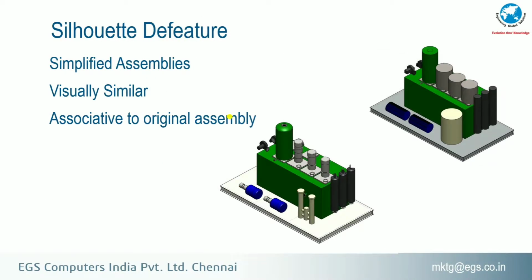Obviously, if you are working with a large assembly, opening that assembly takes much time. The reason is that it contains a lot of features, and every feature gets loaded while you are opening that entire assembly, right? To eliminate that time while opening your large assembly, this year we have brought one of the excellent enhancements, which is the Defeature.